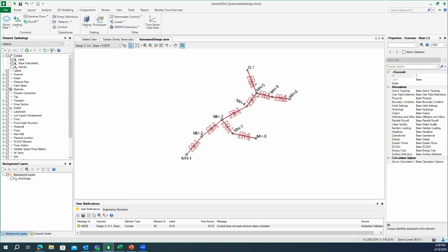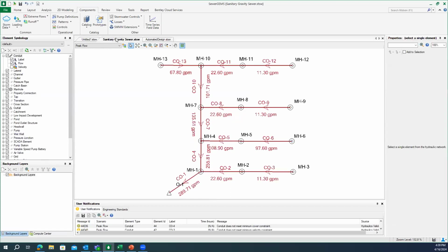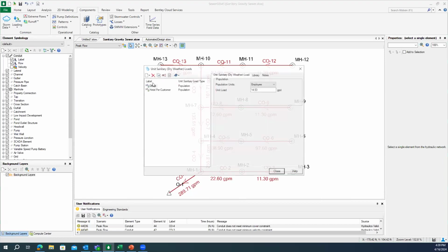How to distribute the population on each manhole? Like you want to assign the load for each manhole, how we are going to assign the load that you are talking about? Am I correct? Yeah, I have just showcased that thing as well. Let's suppose we talk about the loading here, the C1 network. Within the loading, once we talk about the C1 network, we go for the Sanitary Load. Once you select the sanitary load, here you can set your method.